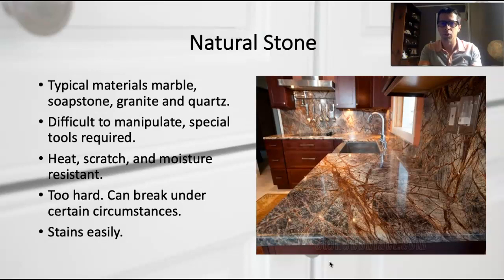Okay, when something's too hard, it becomes brittle, and if it's not properly supported and you drop something heavy on it, it cracks. Okay, so it's the same thing as like concrete. As long as you've got a good subbase under your concrete, it's great. But these materials lack tensile strength. So if it's unsupported on the bottom and it's moving, or if something heavy falls on it, it'll just snap in half. Okay, and that can be very problematic because you can't just glue it back together.